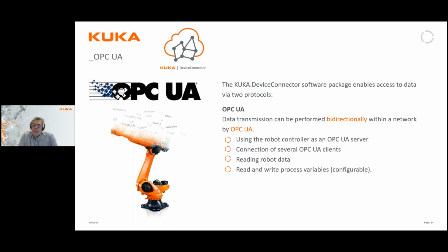If we now look at OPC UA, UA stands for Unified Architecture, and that makes the OPC transfer platform a hardware and software independent transfer medium. OPC has, as many of you know, been around for quite a few years now, but the older standard, OPC DA, data access, was limited to the Windows and Microsoft platforms, while OPC UA is open to all platforms.